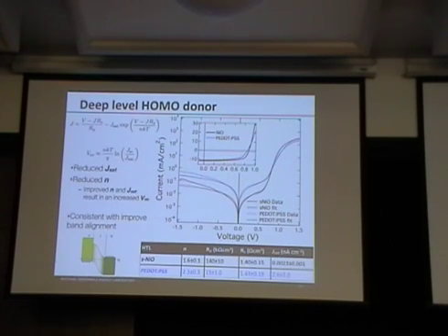It also assumes that we have one diode, one thing that's rectifying in our system. If we have 2 contacts that are both selective, presumably they're both rectifying, yes? Which means we wouldn't necessarily anticipate that the values would have to be between 1 and 2. They may be, but we have more than one junction now. So just something to think about.